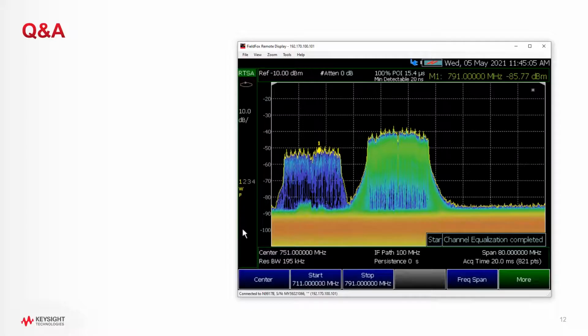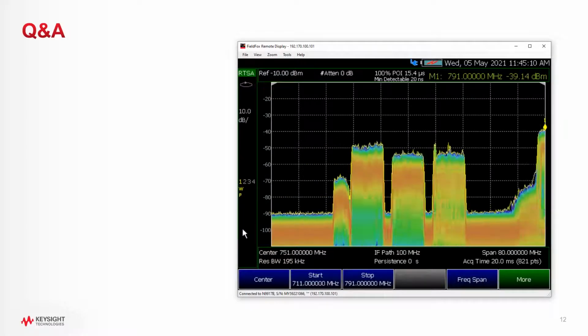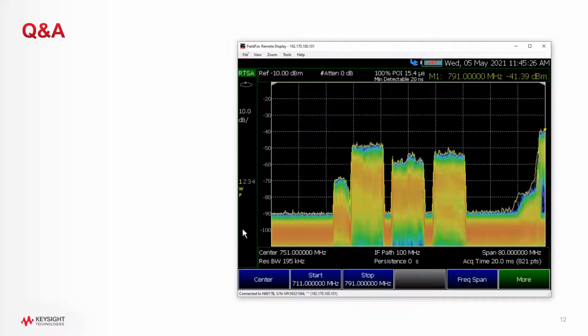Jim has a question. What are the typical Bluetooth interfering sources? For Bluetooth, primarily the issues are around Wi-Fi. It can be Bluetooth. Bluetooth is designed to be hopping, so it's always moving. Noise level can be a big one. If there's a lot of Wi-Fi routers around and the noise floor is coming up, and your Bluetooth is at the fringe of its distance, that can be knocking Bluetooth off.